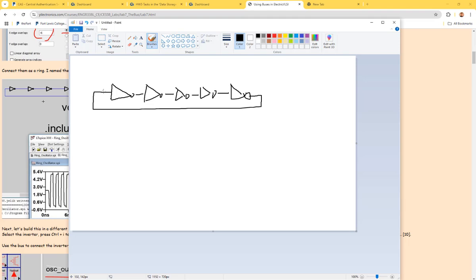there's a voltage here, it won't be exactly 2.5 volts, just to let you guys know. It won't be perfect. So the switching point at 2.5 volts is not going either up or down, so it's not forming what's called positive feedback. So if it's a 0 here at the very beginning, and let's consider this one goes from 0 to 1, because it's getting inverted, there will be a time delay between the input and output, and it will be put down to ground after a certain time delay.